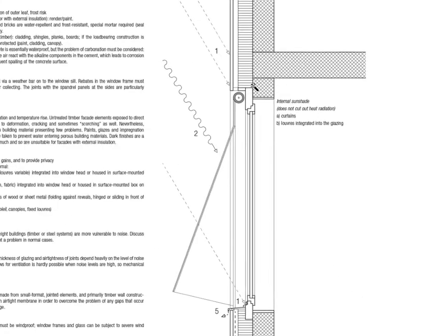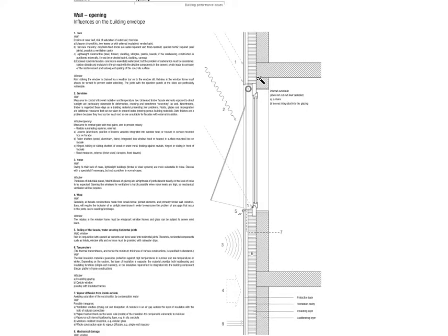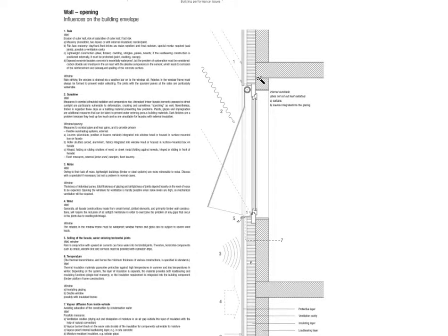So these all have a big influence on the detailing, but nonetheless there are certain basic principles in the construction that are really important for all of them. So overall, and I'm just trying to get my pen out here as well, your window will be part of the insulation layer. So what we can see here is on the outside, the insulation, and your window together with the window frame and the glass will be part of that layer, because both of these parts, the frame and the glass itself, will have certain insulating properties.